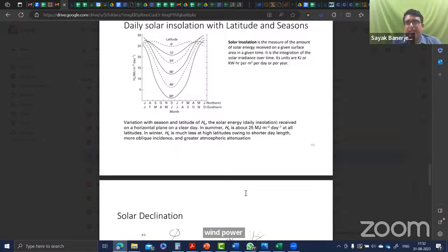The levelized cost takes into account the entire life cycle. So for example, a wind turbine farm will run for 20-25 years. This is assuming that you have a space where there is sufficient wind velocity, like European areas. Of course, if the wind velocity is low, you won't choose that as a place where you want to put wind turbines. So you need to have sufficient wind velocity, as we discussed, the power is the cube of the velocity, right? To get the kind of power output per meter square that makes it economical.